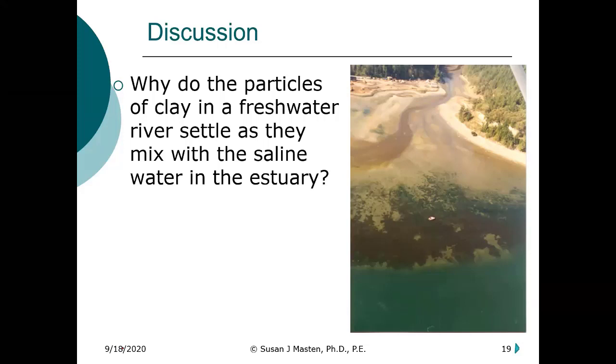about 20 grams per liter. So you're looking at molar concentrations of salt in that fresh water. So as the clay hits that fresh water, what you're doing is essentially adding sodium chloride, compressing the double layer, and you get coagulation. So that's why in the image, if you hold it there, you see that the water becomes clearer. So what's happening is you're getting coagulation right in this region here.